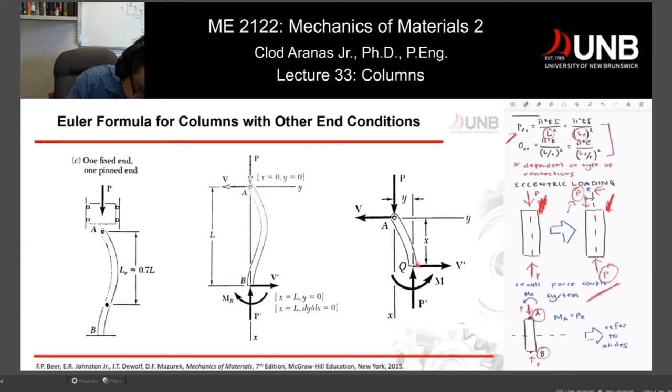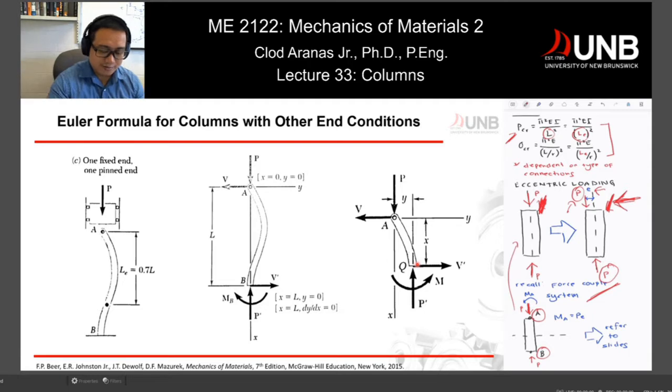Now we can move force P along the center line of our column. If you imagine this top arrow, we can move it exactly to the center, similar to the one on the left side here. But since we move it, we have to apply the corresponding moment. And what's that corresponding moment? If we go back to this second column here, you have P times e.